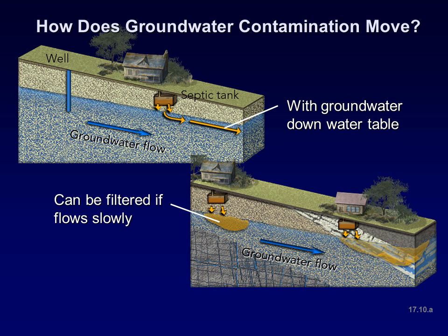It's important to consider the direction of groundwater flow when siting the relative positions of a well and contamination sources, such as a septic tank. In general, put the well uphill of a septic tank, but be aware of what is farther up the hill. Okay, so even if this guy on the right with the leaky septic tank and water that's flowing slowly decides to put his well uphill, depending on how quickly that tank from the house on the left has its contamination flowing, his water well might get contaminated as well.